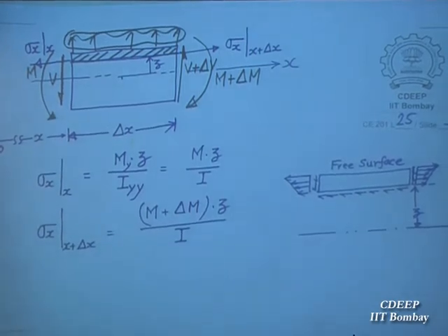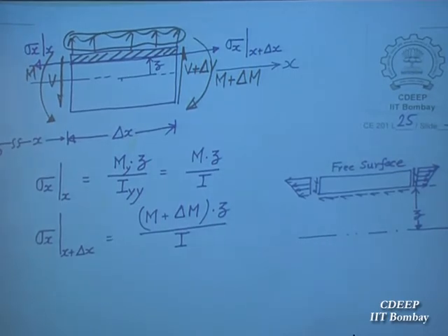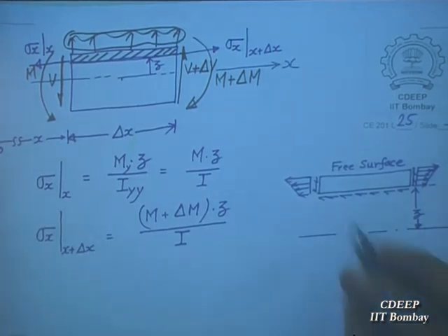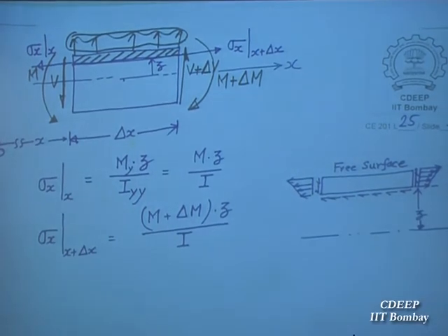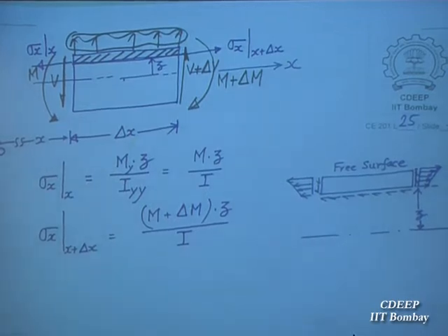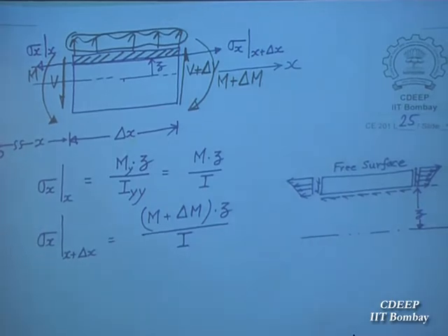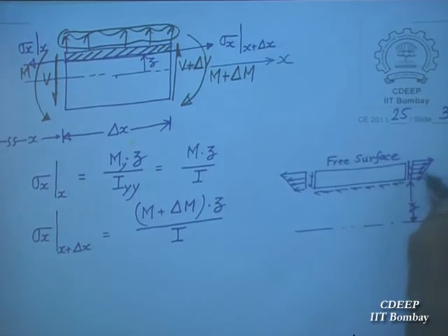Can there be also normal stress? Yes. Namrata? Here normal stress, I can also have a normal stress. But I have told you right in the fourth assumption in the beam theory, we have assumed that normal stress is a very small quantity compared to this stress. This stress is sigma x.